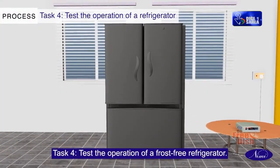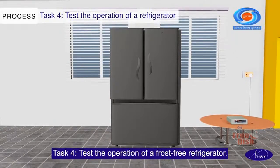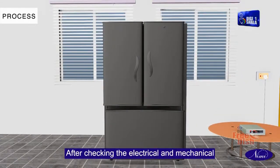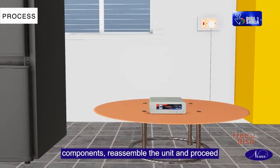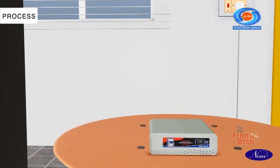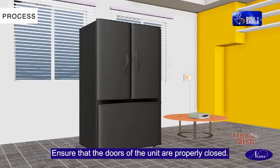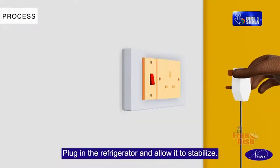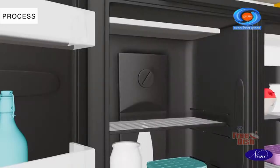Task 4. Test the operation of a frost-free refrigerator. After checking the electrical and mechanical components, reassemble the unit and proceed to test its performance. Ensure that the doors of the unit are properly closed. Plug in the refrigerator and allow it to stabilize.